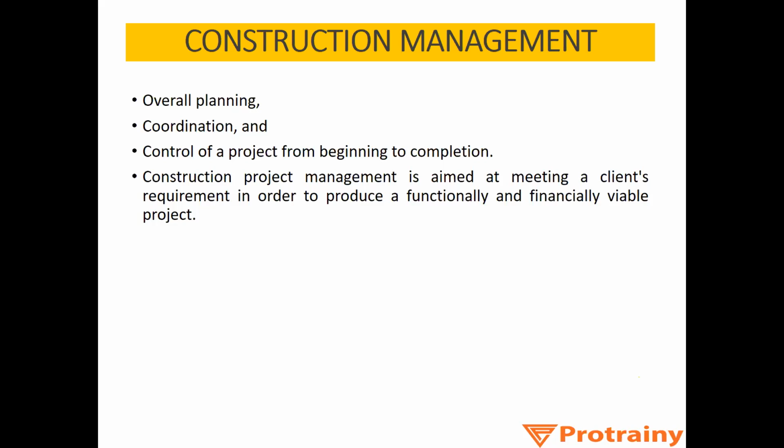Now we will email and coordinate with architects, structural engineer, MEP consultant. Then they will check the drawing, they will respond, they will send you a revised drawing. So this step is anyway going to take 15 days. So what effective construction management is: if someone from the construction management team had already seen this issue, that all the three drawings of the same floor have some differences in them, this 15 days could be done before you reach that particular slab or that particular floor of that building.